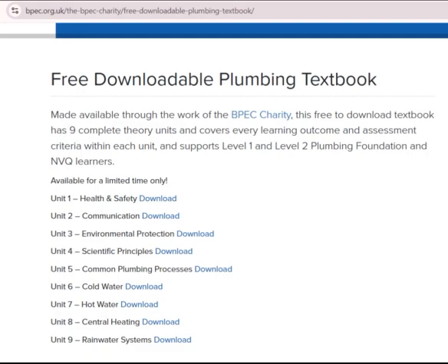Antifreeze/glycol mixes. Glycol, when mixed with water, is used as an antifreeze in solar hot water systems. It protects solar panels from freezing during the winter when added to the sealed solar panel circuit. The antifreeze solution should be checked regularly as its antifreeze capability diminishes with time and the solution can become corrosive the longer it is in the system.